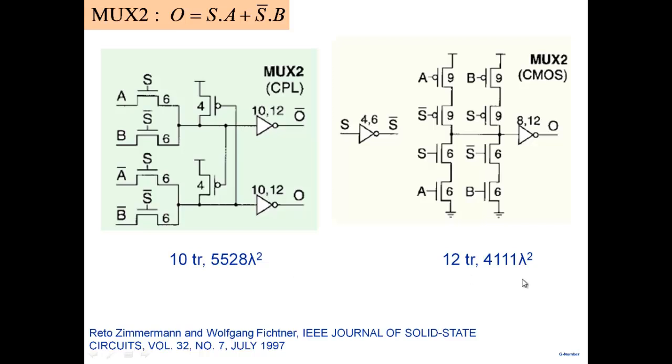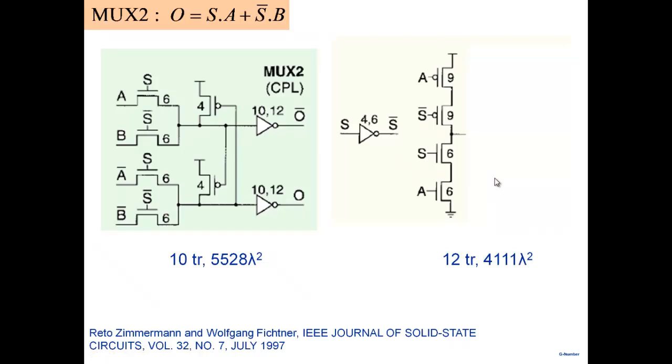Now, look at this particular one. This is not a regular CMOS. Can you see that? A regular CMOS would have whatever is in the pull-down network, with the exactly complementary part in the pull-up network. It's not a regular CMOS, but there is an NMOS part and a PMOS part here. If you note, it works very interestingly. Let me remove this particular part here.